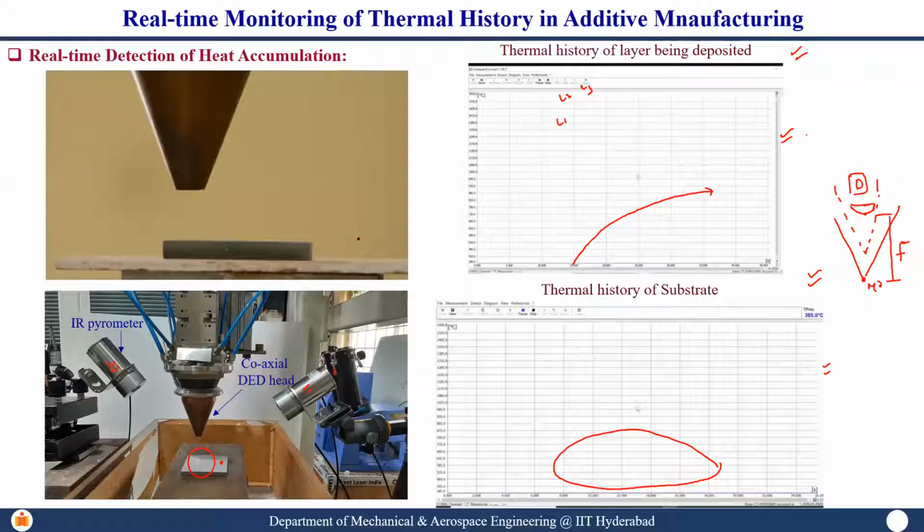The first thing you need to see is how close your powder particles are to circularity. The other thing is, if you want a hybrid or composite, typically we go with pre-mixing of the powders in a metered quantity and then blow them.